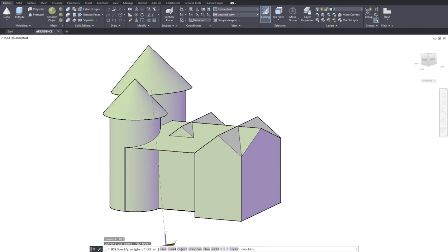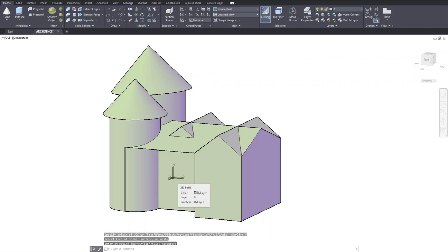One of them is face. I will go with the face option to select, see if I can locate. Face is going to be the entrance. Basically, I'm moving my cursor over the face and entrance and enter. Okay. So at this point, I'm ready to create my door step. Door step is going to be about 9 inches higher than ground line. That's very important to remember.